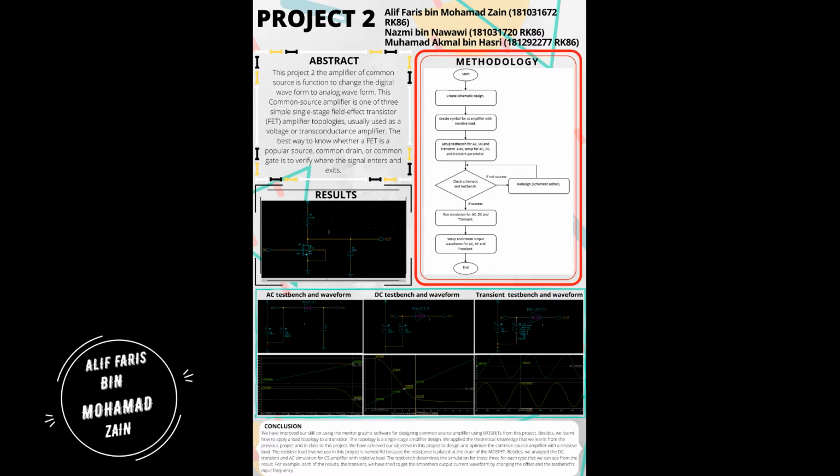For DC, the gain of the amplifier is increased with increasing width and decreasing length. The RO resistance appears in shunt with RD because of this. The effect of RO decreases the voltage gain of the amplifier. On the other hand, the effect of the parallel combination of RO and RD decreases the output impedance Rout, which is